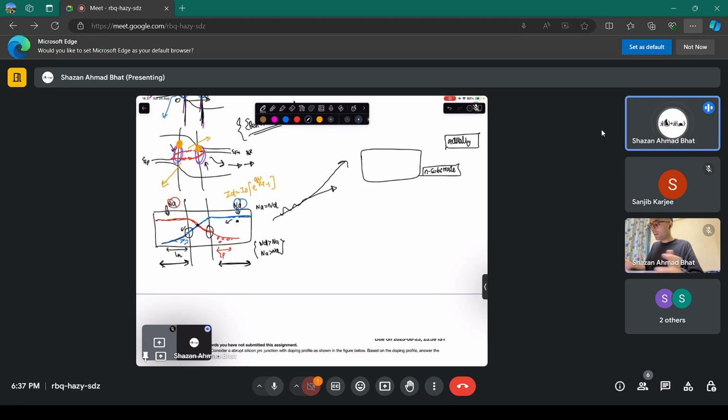We take an N substrate, a single substrate of N-type silicon, and by using certain processes, you dope it here and make a certain region, called a well, and this particular region is P-type. So this is what you get. This is where you get a kind of depletion region. You get positive charges around this side and negative charges around here. So this is the actual structure of a diode, how a diode is made.